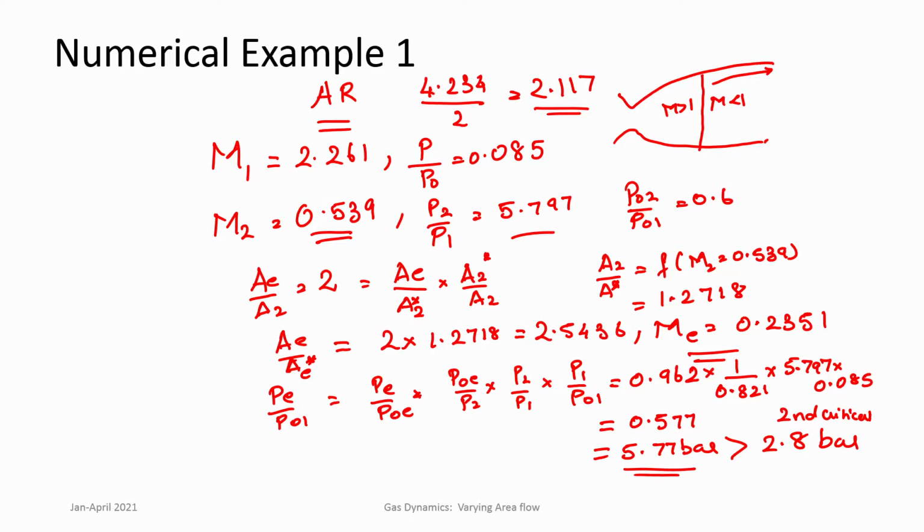Once the pressure ratio is continuously decreased after that, supersonic flow starts in the divergent portion, but it may not last until the exit. The limit of that is supersonic flow all through the divergent portion, but there is a shock at the exit. The exact operating condition is when there are no shocks at all and the nozzle expands so that the exit pressure matches the back pressure at supersonic flow. That is known as the correct designed operating condition.